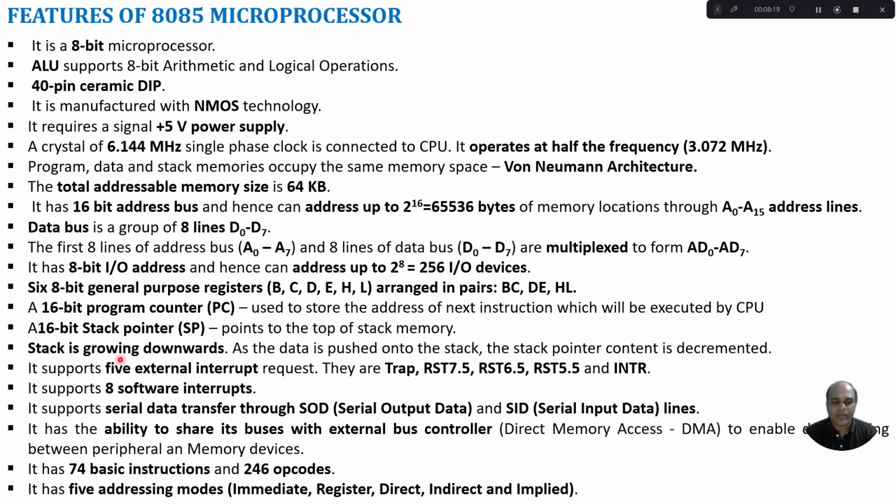And the stack grows downwards, meaning as I start pushing data onto the stack memory, the address will get decremented. As I start popping the data out of the stack memory, the address will be incrementing. So the stack is growing downwards.